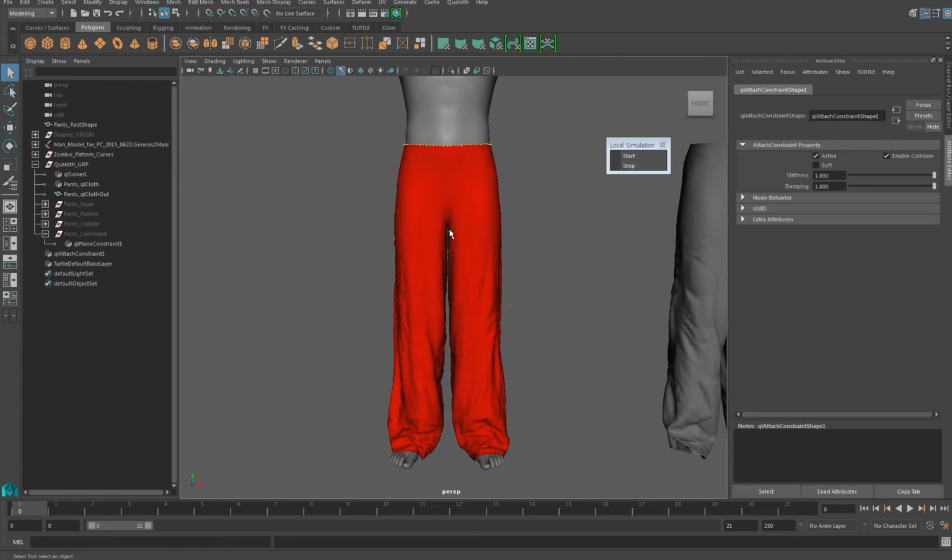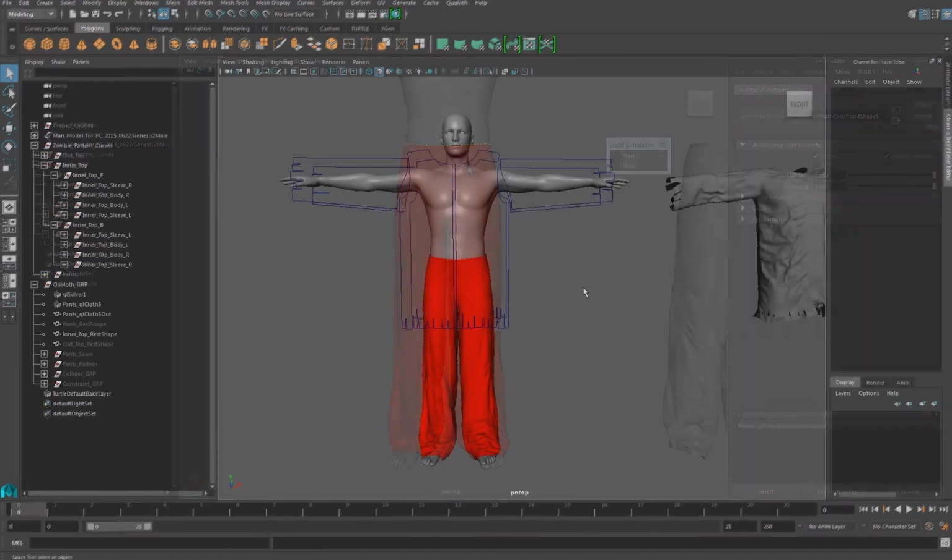Attach constraint allows us to have selected vertices to move along with the object's surface as it is attached on it. So it is often used when you need to make the costume to move along with moving character. Let's attach specific vertices on character's mesh. It's better to keep and manage the costumes that are made for building and shot production use separately. Create other cloth. For now, we'll make the inside of the top cloth.